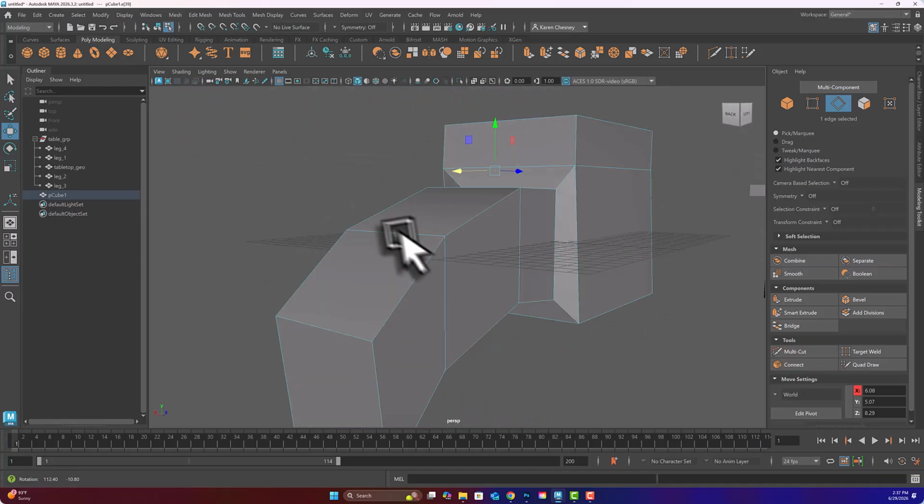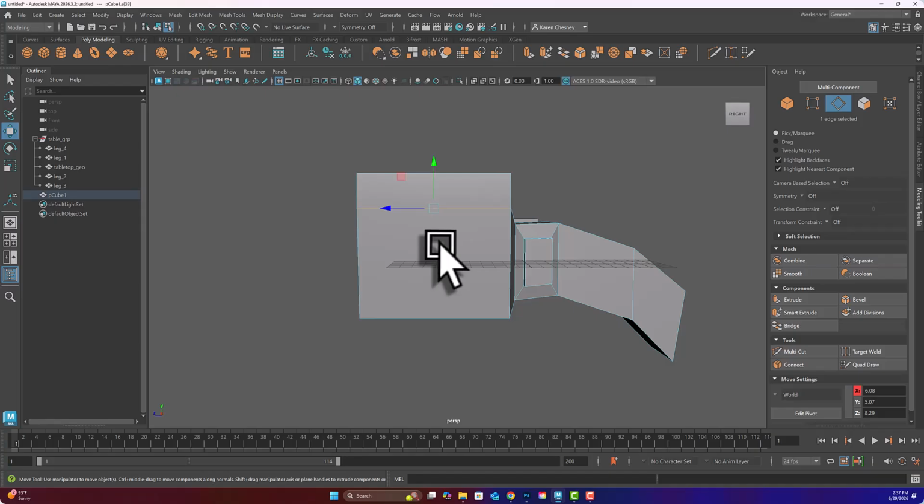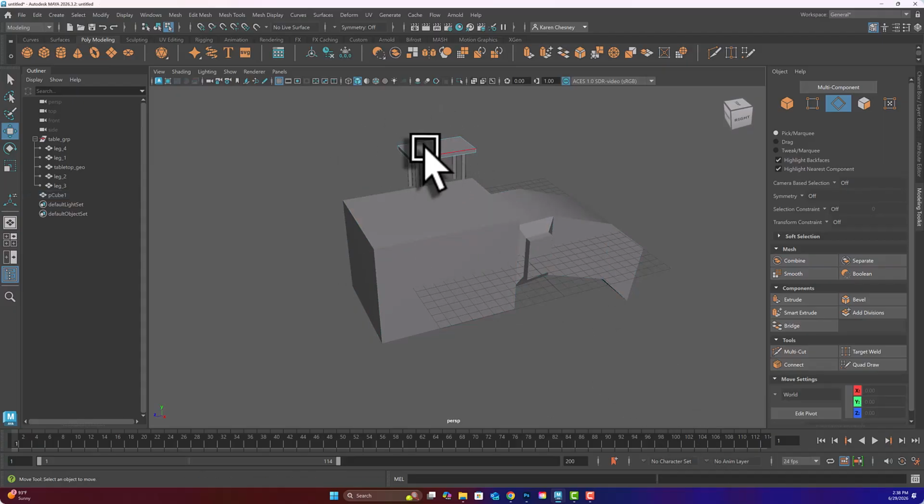Okay. So remember that Maya generally, like a lot of programs, will step back about 20 times. So if I've done less than 20 moves, I can Control Z back before that poly extrude. But if I did it over here on this table a day ago, I can't fix it. And it's way easier to just delete it and redo it than to try and fudge it around and fix it. Okay. But the best habit is to just not double extrude to start with. All right. So there you go.